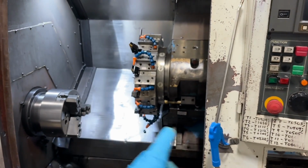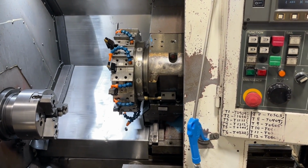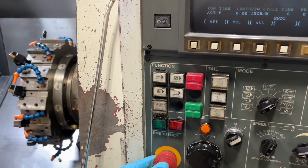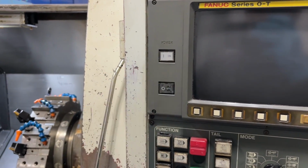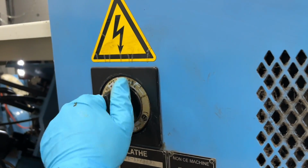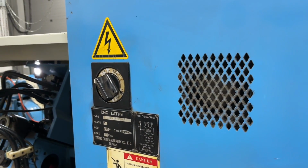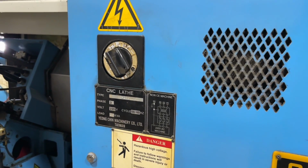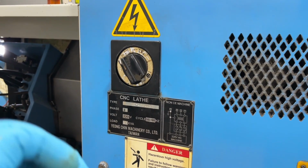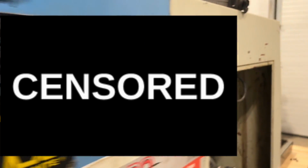Step 1, once your machine is jogged into the middle somewhere, you're going to turn off your e-stop, turn off your main power, and wait 20 to 30 seconds. All right, it's been 20 seconds. So step 2, turn the machine on.